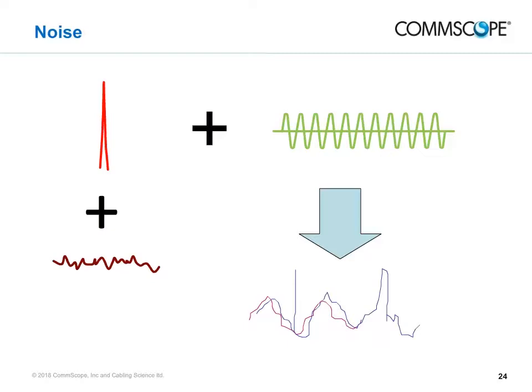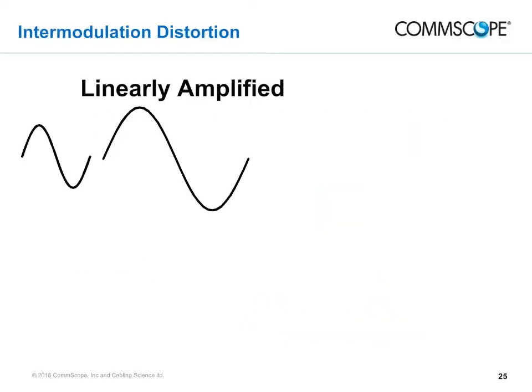Another type of noise that is particularly vexing in cable system upstreams is ingress noise. This noise is electromagnetic interference generated by devices that have an electrical or wireless path to a cable system, typically through power systems or faulty shielding in cable plant. Examples of sources are paths through TV set power supplies and ingress via improperly installed F connectors. The bottom line on noise is that when it is present on a transmission line in any form, it is added to valid signals, resulting in signal distortion.